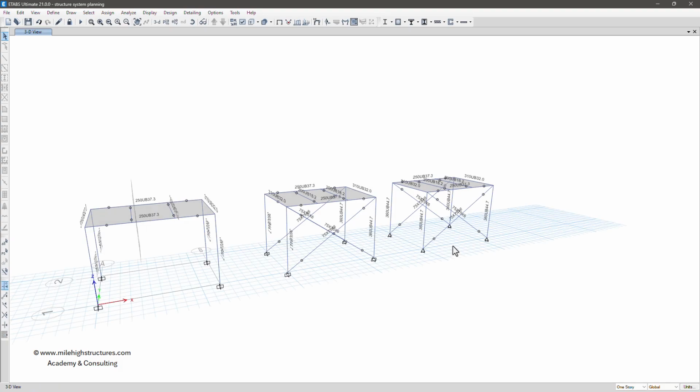So that is the fundamental difference between braced and unbraced frame, moment frame and shear frame, the fixed base at the bottom and pinned base at the bottom. So I hope the concept is clear to you. This was just a basic introduction so that you can understand how the steel structure behaves with bracings, with secondary beams and with primary moment taking frames.